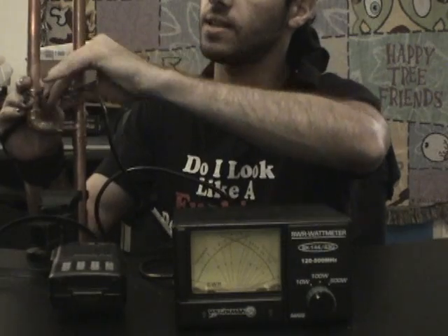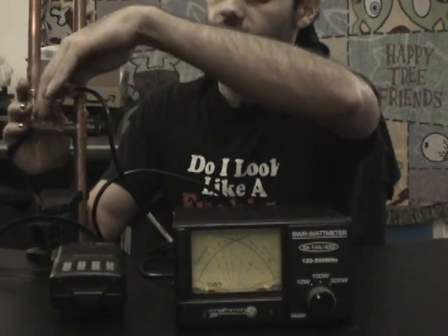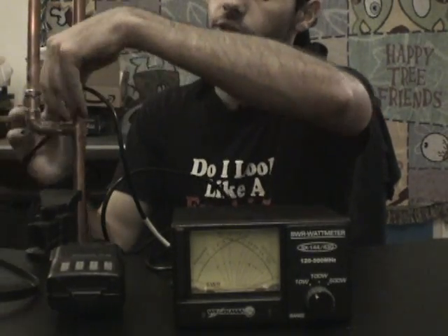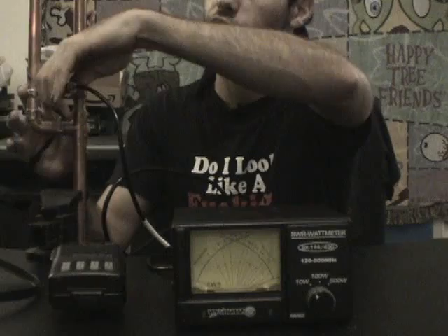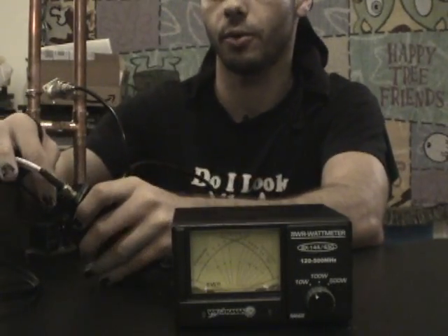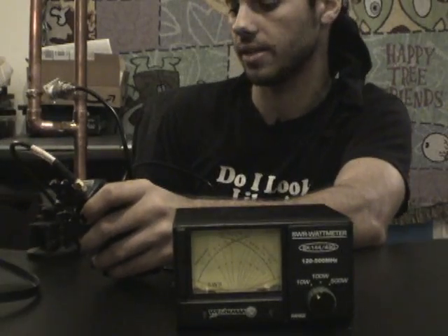Now, what Ophidian failed to mention, unfortunately, in his SWR segment, is that SWR meters need a minimum of 1 watt of power output to function properly. And another thing about these J-pole antennas, you really don't want to have any metal or human beings within about 2 or 3 feet of them, otherwise they'll actually throw the SWR ratings off.